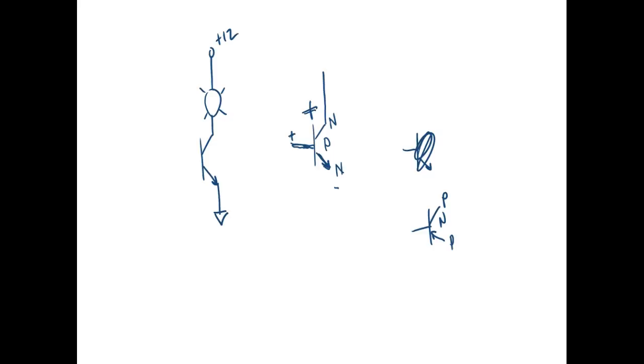Understand that? Okay. So right now it would be off. Why? Because there's nobody over there flipping the switch. We got to have a base. So what I would do over here, we got two options. Right now we'll just come over here and do it this way. Because I'm going to put a resistor there, and then I'm going to come over here and say we put a push button. And then we'll come over here and connect this plus 5 volts.